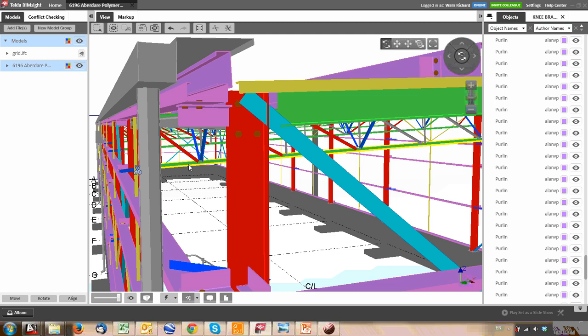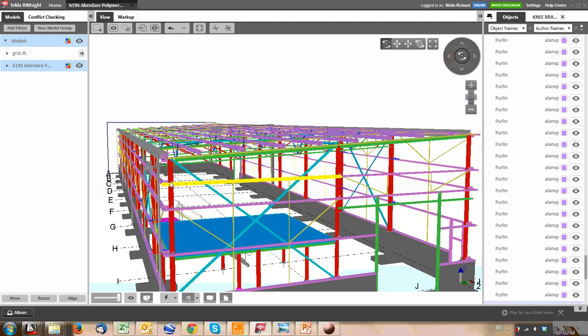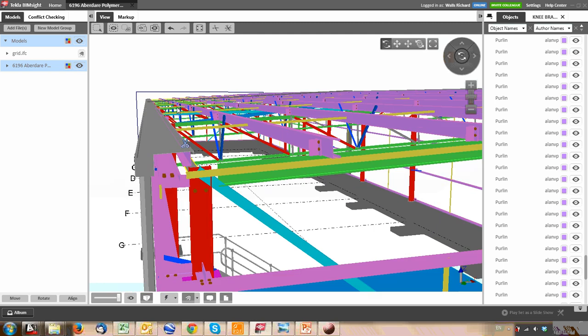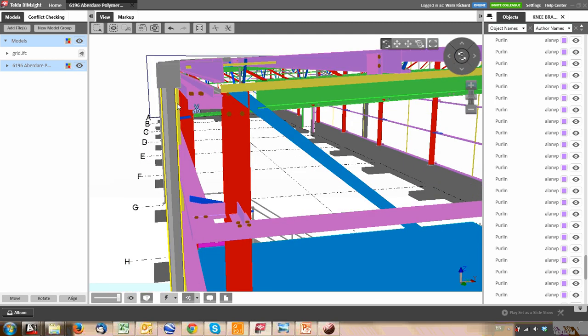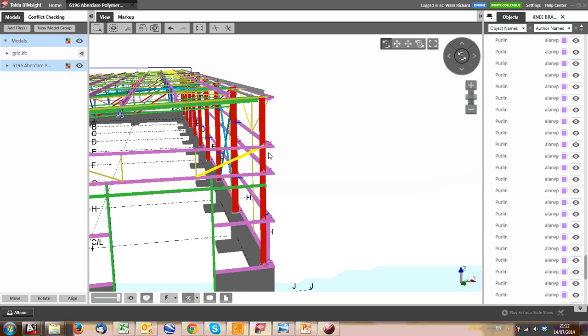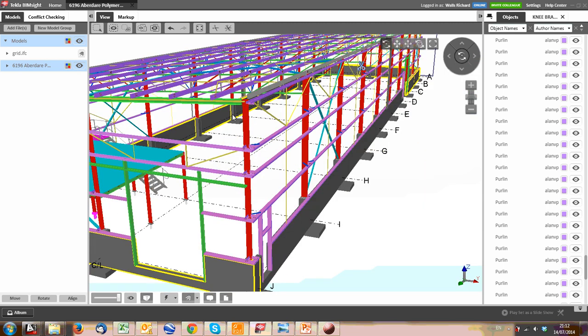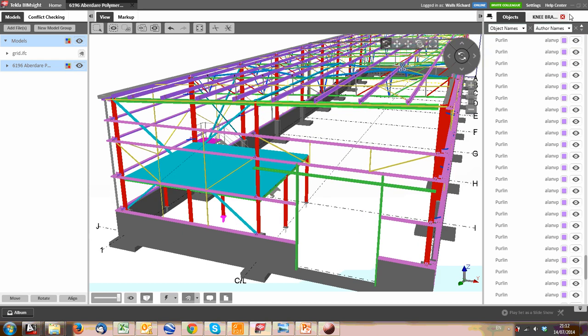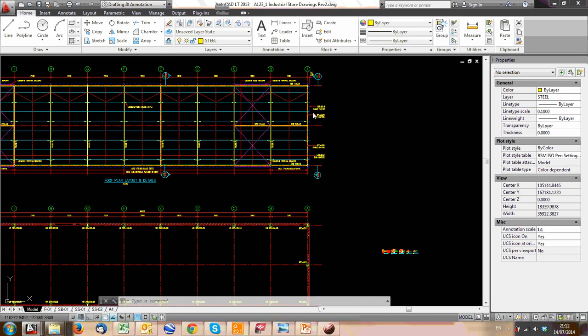On the side, sometimes you just make sure your girt is high enough that it can pick up the sheeting. Or what you have to do, you can even get inventive and put something on the gutter, but just be very careful if you're fixing sheeting to gutters. Yeah, so there are various ways, but you just always have to make sure you've considered the sheeting and where you fix it and how you fix it and will it leak and all those sorts of issues. But let's go back to this.